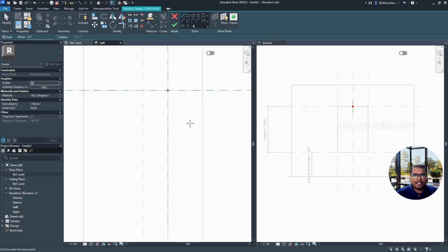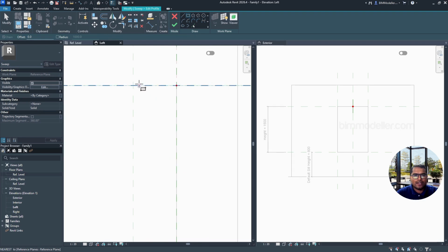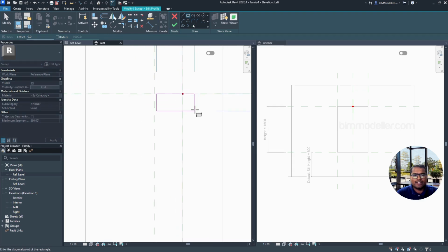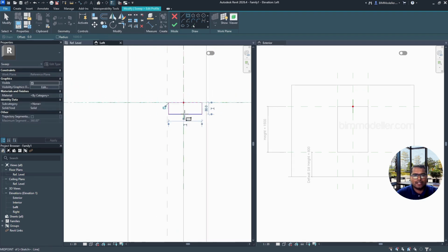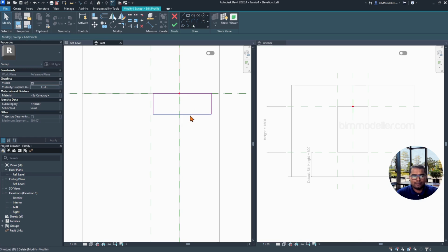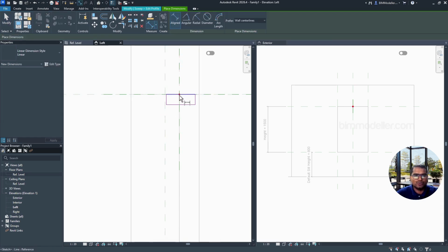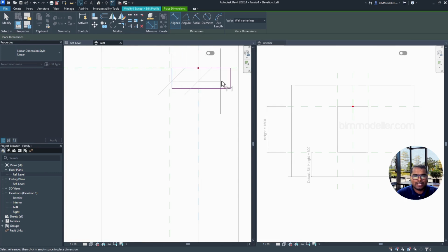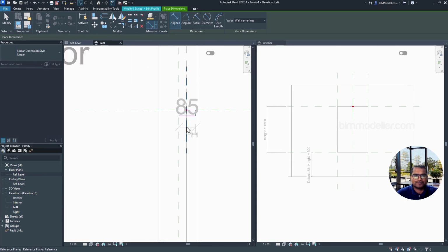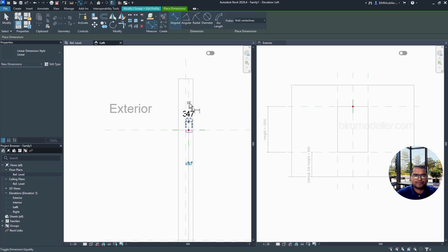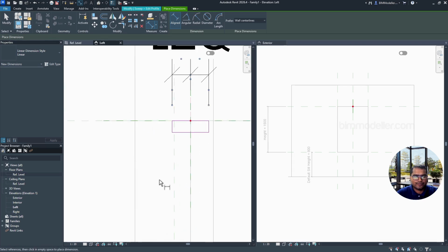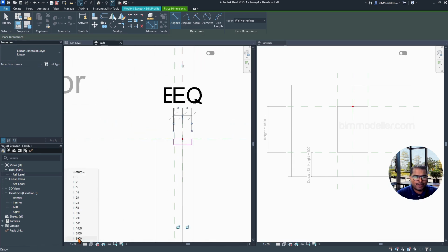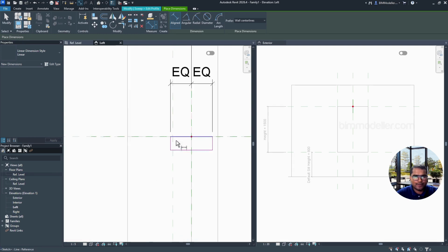We can see that the profile, we're going to draw it here. If we need, we can have the exact middle portion as well for the glass groove. We can have that, and I'm going to make an equal constraint on each side. And let's make this dimension small.